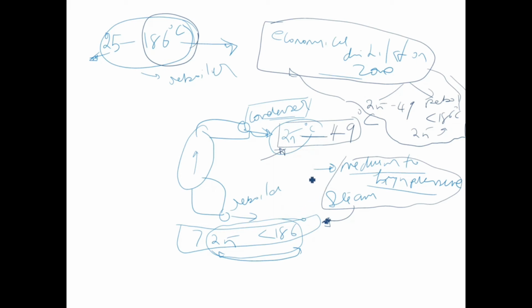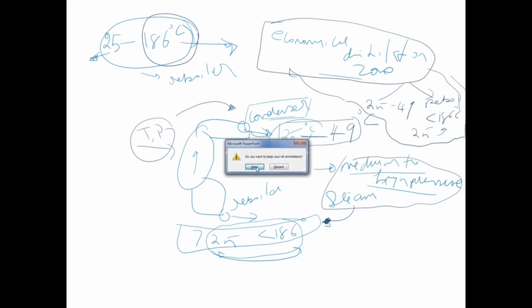Yeah? So whenever you are going to design a distillation column, keep this temperature range in mind and try to play with the process conditions. Check whether changing the inlet temperature and pressure, if you change some values here, allows you to operate your distillation in the economical distillation zone. Okay, so let's do that using Aspen HYSYS. This is something you have to keep in your mind before touching the software. So let's go back to Aspen HYSYS.